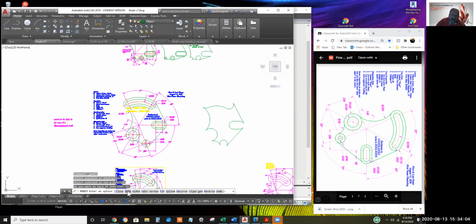So I can click on join option here. I believe I told you day one I'm going to try to use a right click to get to the options. So either way, I'll invoke the join option. Don't forget you can type J enter. Some options have 2 letters you got to type. Anyway, one way or another, I'm going to invoke the join option of the p-edit command.